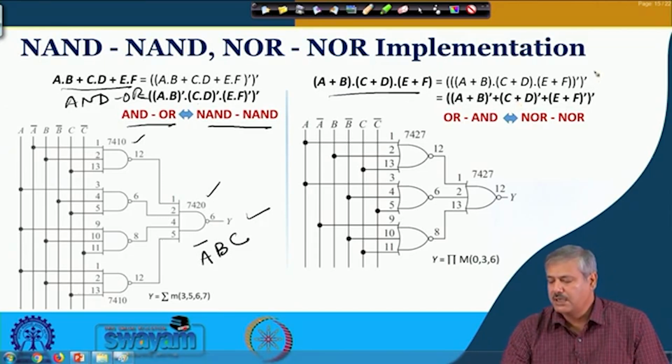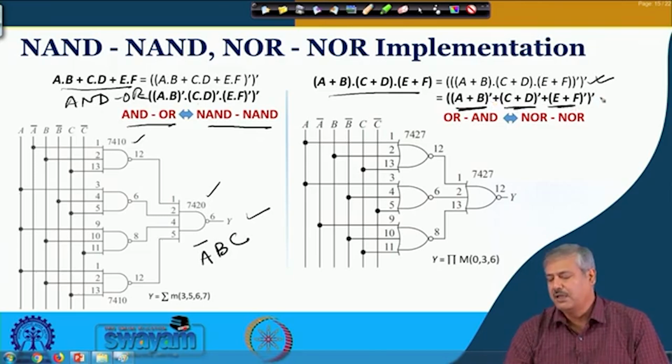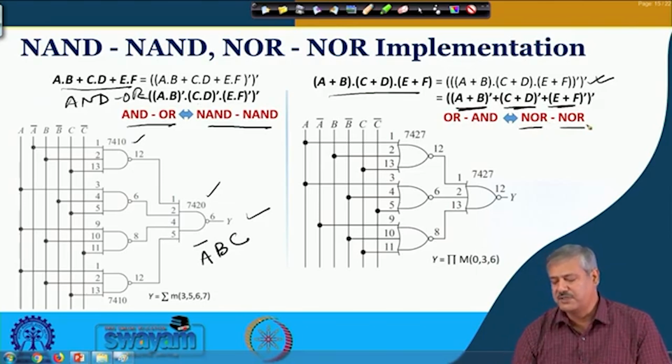In that case again you take the double complement, and then use De Morgan's theorem. So, this is one NOR gate, this is another NOR gate, this is another NOR gate, and finally a 3 input NOR gate combines all of them and you get a NOR level representation. Similarly, for this particular example we have one NOR bank followed by another final NOR output stage, and we can get the same result.